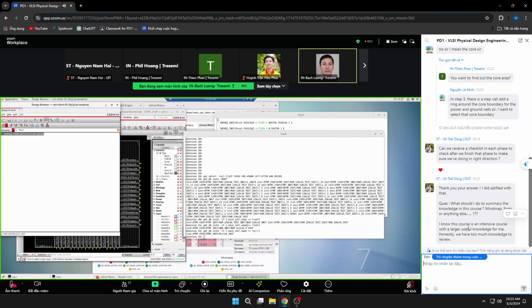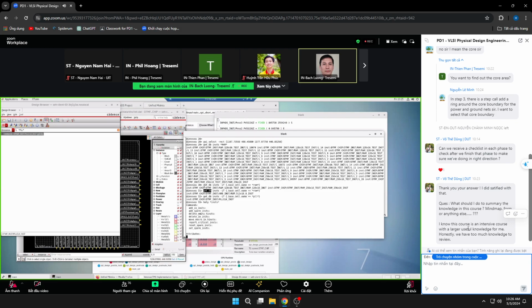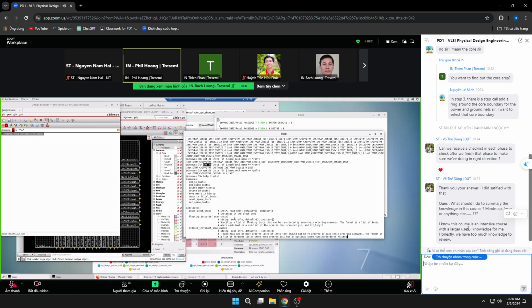You can do the same thing for any particular instance name that you want. You can use the get_db instances command. Okay, if you don't know how to do get_db instances, you can do a help star instances, and it'll come back with a whole bunch of options for where you can grab it. And the PLL instance, you can see the whole path, and in your instruction, actually, it has that whole path, right? So you pretty much don't need this, but that's how you select, right?